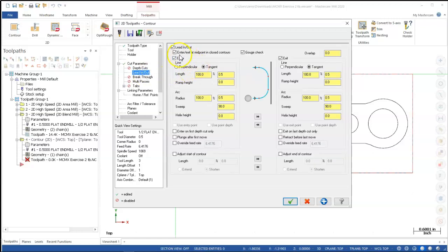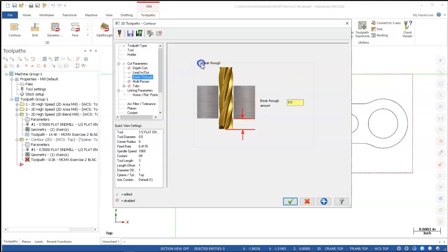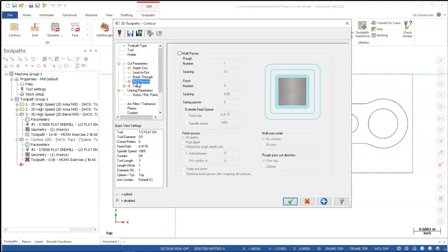So the lead-ins, we're going to need to be pretty small. So I was 1/2 inch tool on a 3/4 inch. So these are going to come down to maybe, let's go 20 thousandths, since it's starting really close. And then I'll transfer it over. Breakthrough, we'll stay with the 10 thousandths. And then multiple passes, no, don't need to work in or out.